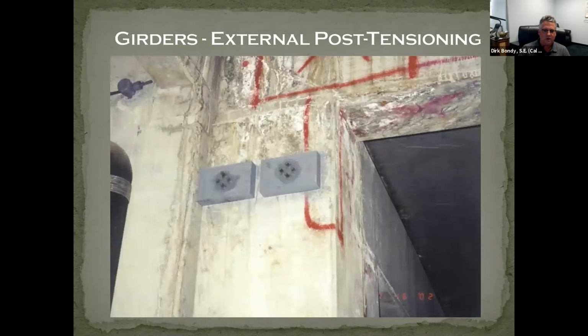But those are large forces in large cored holes, cored at an angle. So like I said, this is where a really good qualified contractor comes into play. Coring at an angle is not easy. They can all core flat. They can all attach their coring machines flat and perpendicular to something, but to get somebody to core at an angle isn't easy.